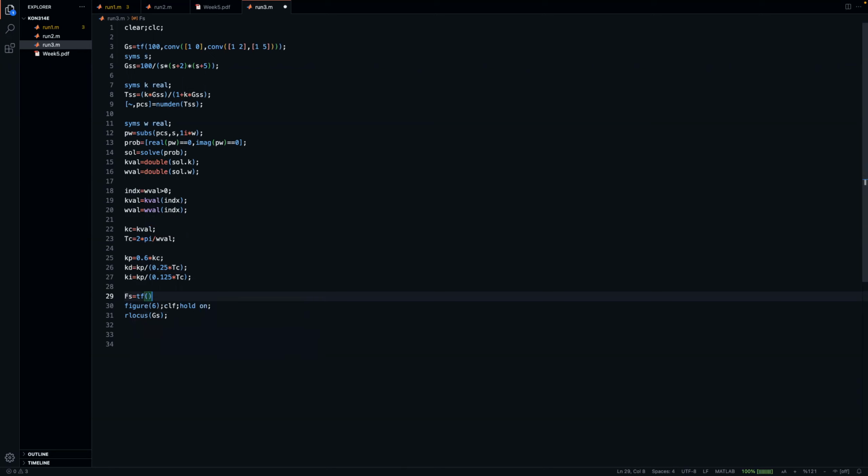So this is an interesting thing, because it's not looking at whether the model is a certain order, what the poles are, or what the zeros are. We are not really interested in all that stuff. All that we are interested in is how it behaves during marginal stability. Here, T critical is basically the period of the sine wave that we have.